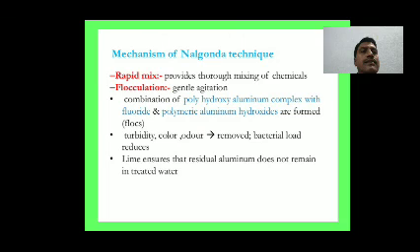A combination of polyhydroxy aluminum complex with fluoride and polymetallic aluminum hydroxides forms floc. Turbidity, color, odor are removed from water. Bacterial load is reduced. Lime ensures that residual aluminum does not remain in treated water.